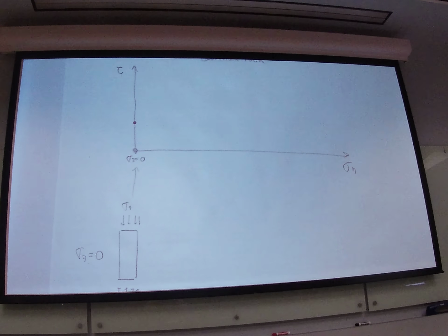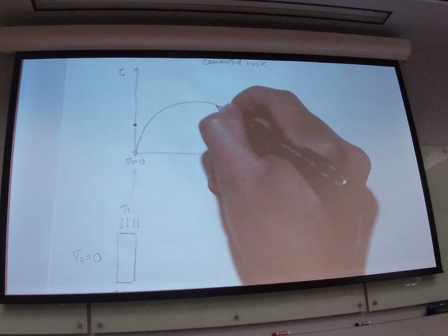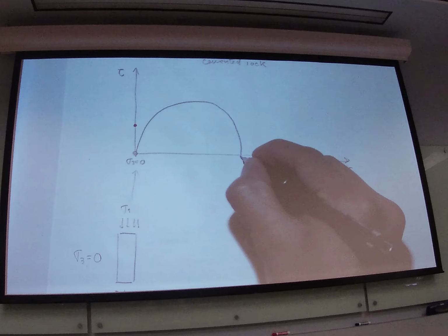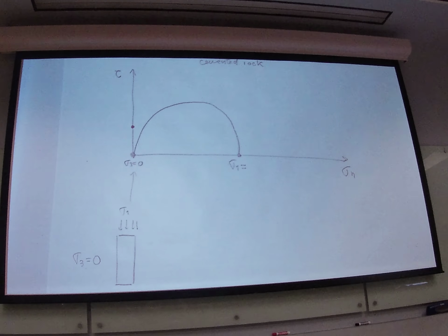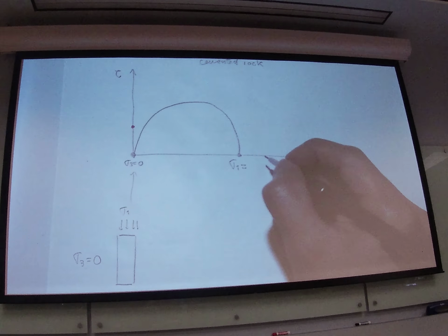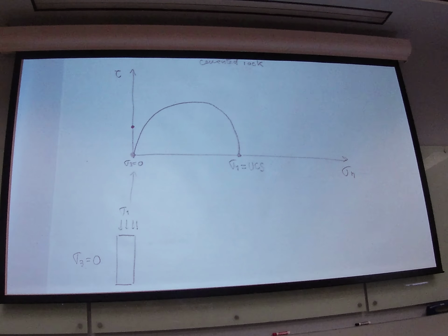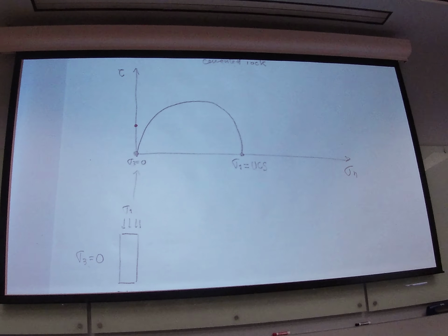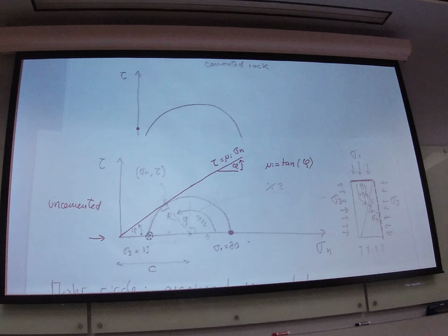But even if sigma 3 is equal to 0 in a cemented material, still I can load it to a sigma 1, which is not equal to 0. And if this is a failure, we call that value sigma 1 the unconfined compression strength. If I were to subject now this cemented material to a confined stress, I'm going to see something similar to what I saw before.